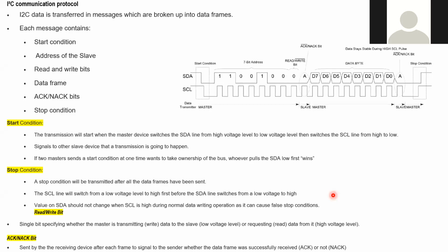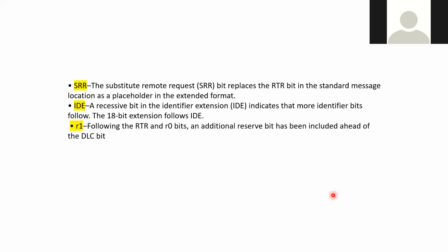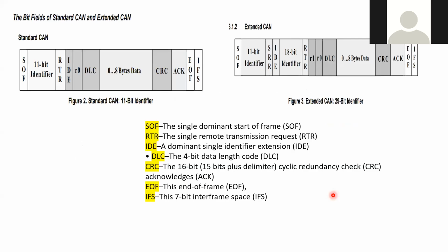Okay. Now a very big thing: at least tell a few parts of the CAN protocol. What do CAN messages contain? Data frame, remote frame, ma'am. Start frame. Error and overload. No, you forgot. I took a very big time to explain. Ma'am: start of frame, arbitration, control field, data field, CRC field, acknowledgement, end of frame, ma'am. Very good, very good, very good.